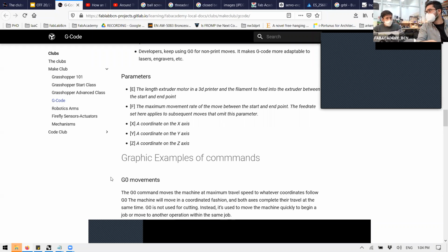For example, my Cura is configured like that. I hit both things at the same time to save time because I don't want to wait. Or hit the extruder first and then the bed because one takes more time than the other. Or switch on the fan while it's heating, or home at the same time that it's heating. You can change how the machine behaves on its own.